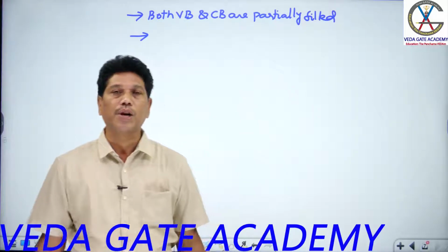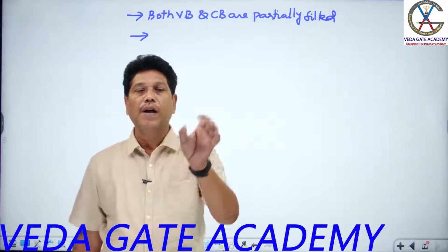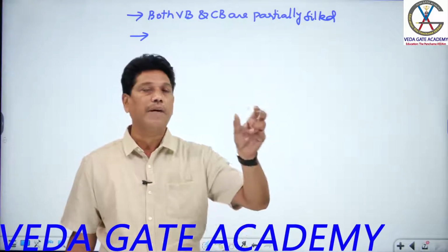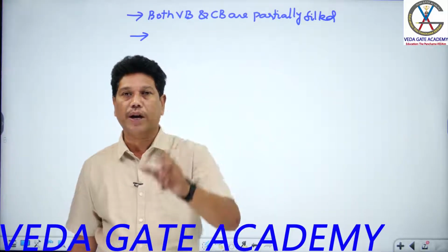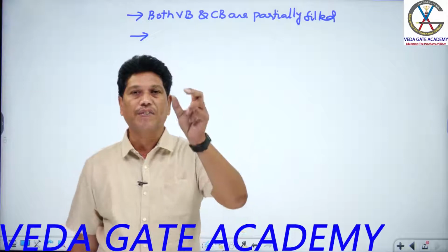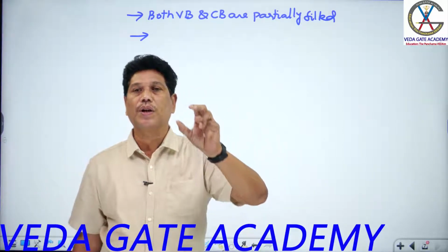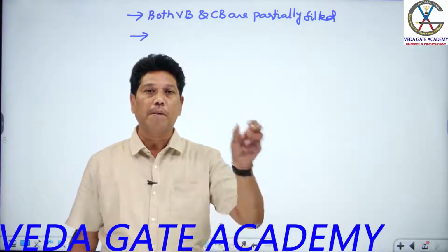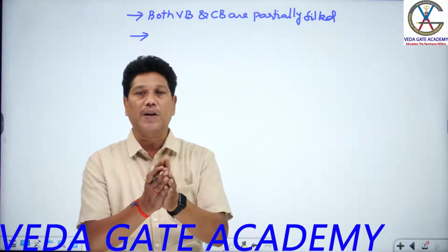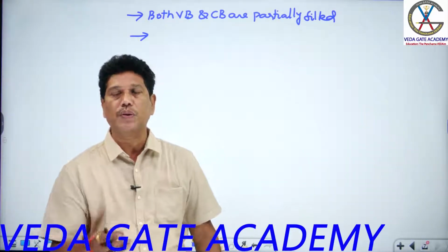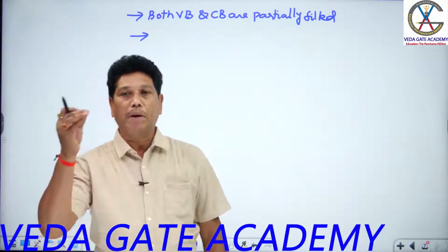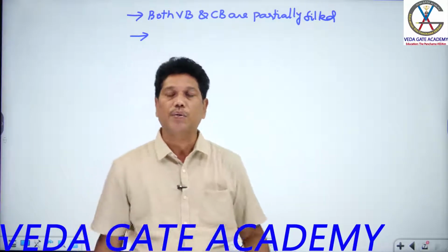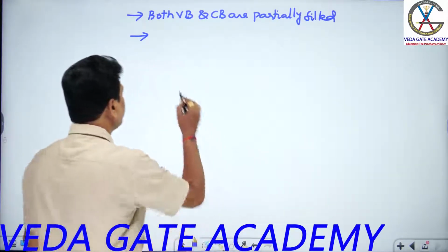Remember now, students, V equals IR is the statement of Ohm's law applicable for both conducting and non-conducting materials. For any material, you can use that formula V equals IR, using which you can define the resistance in accordance with the voltage and current relation. But one more Ohm's law is applicable only for conducting materials like conductors and semiconductors, students. For conductors, it means current density J is proportional to E.